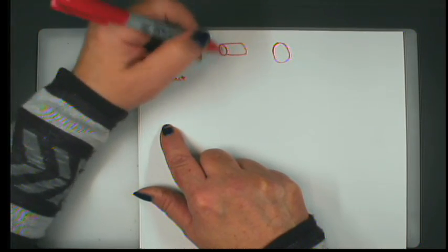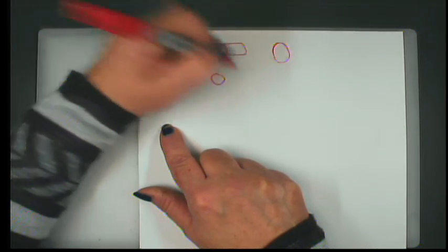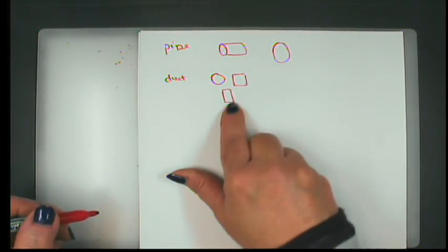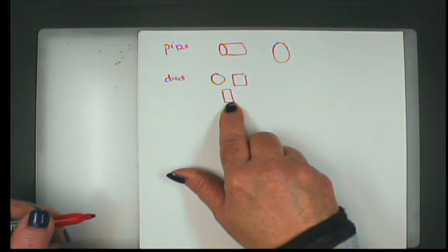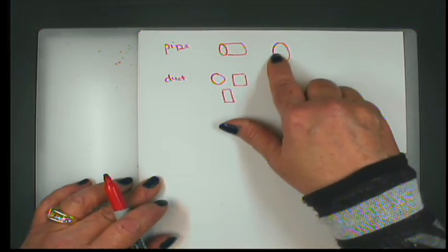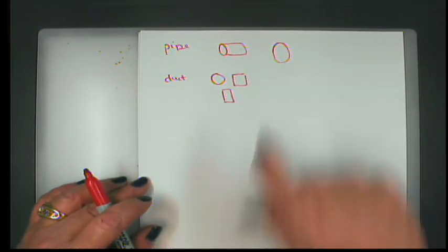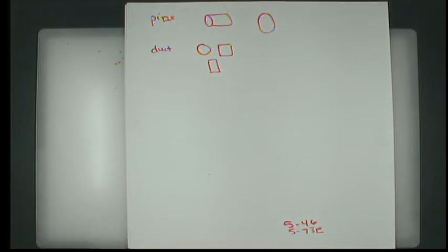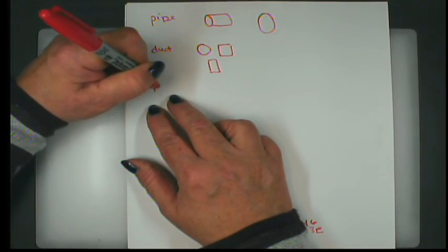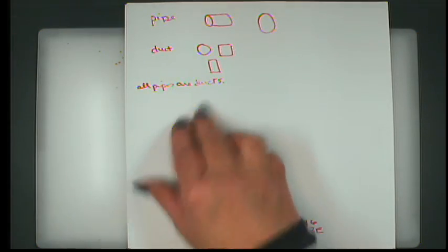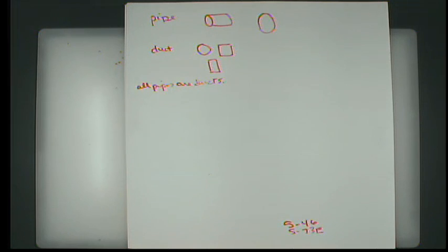It can be anything. A pipe is a duct, but you can also have square or rectangular cross-sections as well. These are more typical for transporting things in the vapor phase. Most of the time water, because it's heavy, or any liquid will have either round or elliptical cross sections. And that's the difference. So all pipes are ducts, but duct is a more general term. So there's things that are ducts that are not pipes. Exciting. Let's take a look at one.